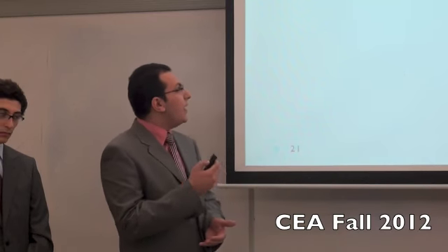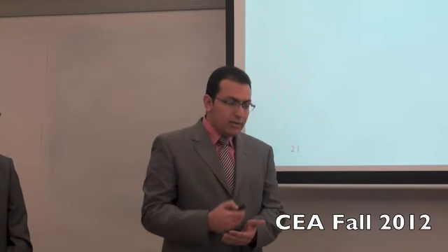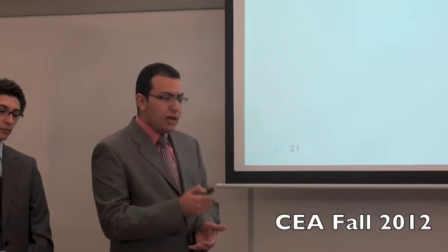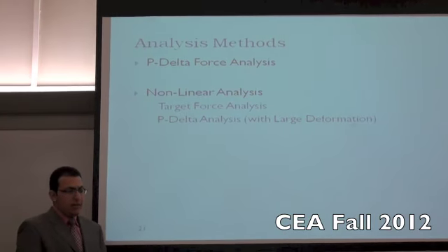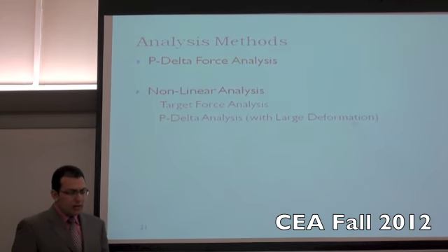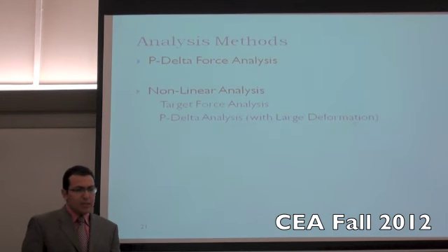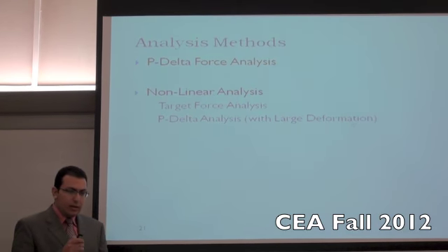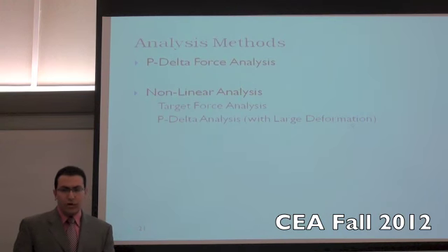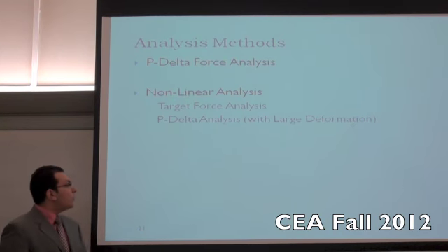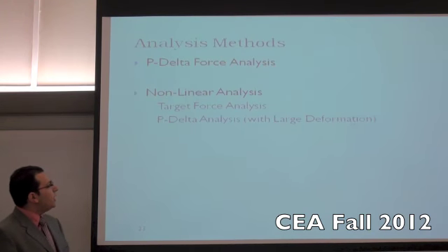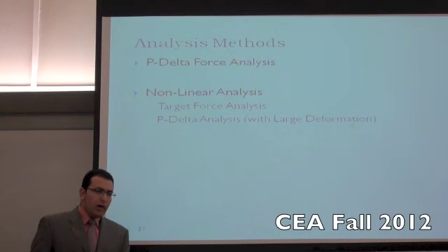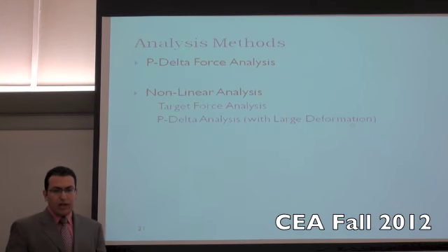There are 2 types of sub-analyses under that umbrella. The target force analysis is quite the same as the p-delta force analysis. However, it did not yield good results because it has to converge to the certain number that we inputted in the software. So we resorted to the p-delta analysis with large deformation. That type of analysis takes care of the large deformations, the p-delta effect, and the bridge behavior.